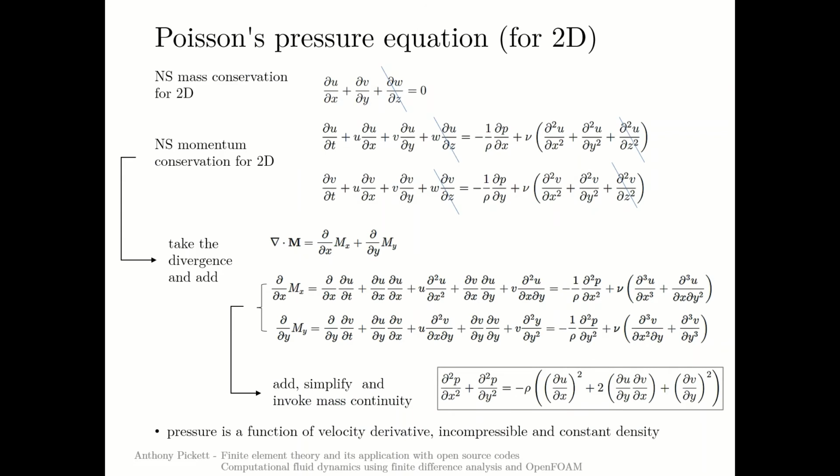Another important point is that we're dealing here with an incompressible liquid, and it's isothermal, so we don't have temperature as a problem. Now we have two sets of equations that will have to be solved. We have the mass conservation equation, and we have the momentum equations. We don't have to worry about energy equations for an incompressible non-thermal problem. So in that respect, it's fairly straightforward.